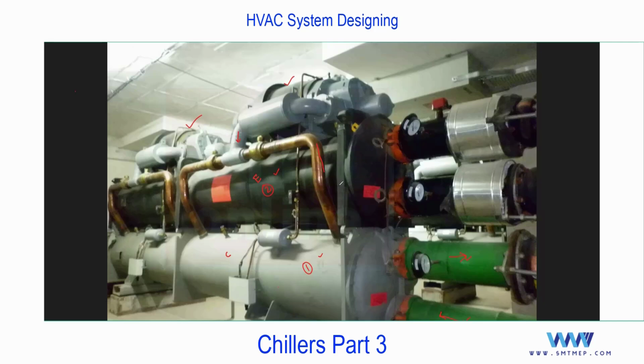So you'll find two shell and tube. And because of this, you'll find three cycles in this. One cycle is what? The vapor compression cycle. Same. Compression, condenser, evaporator, expansion, you know all this. The second cycle is a chill water cycle, same as air cooled. And the additional cycle in this is what? Condenser cycle, which will connect to the cooling tower with a separate pump. And why the need of this cooling tower? And how to cool the water which is used to cool the refrigerant. That I'll show you with the line diagram.